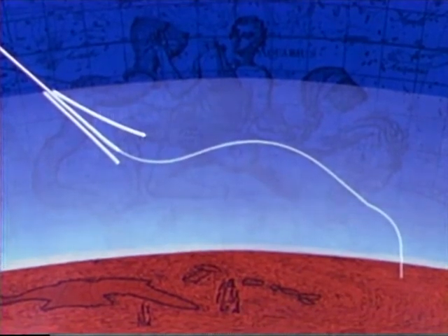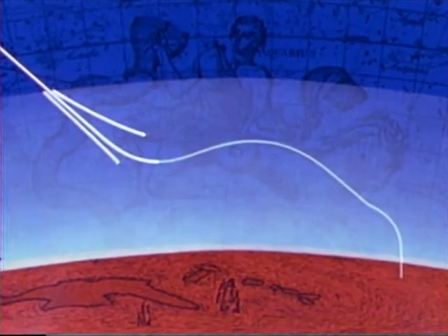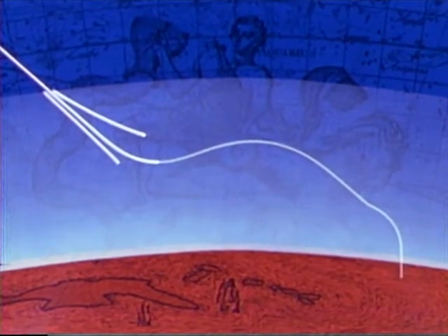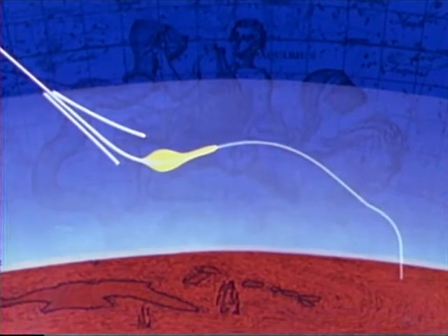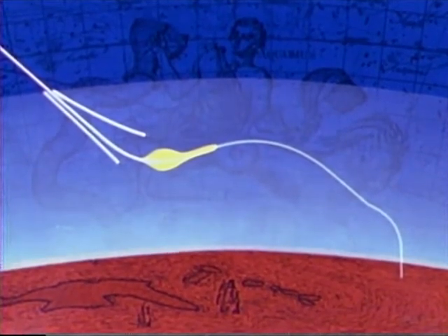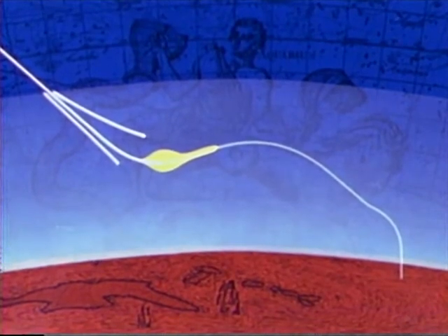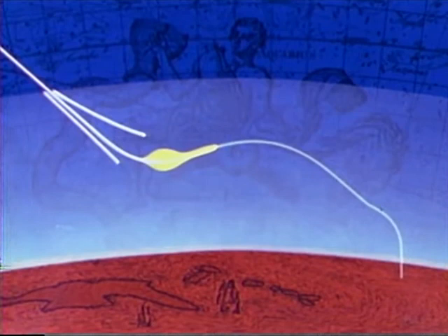The spacecraft continues in a lift-up attitude until it enters the dense portion of the atmosphere. Just before pull-up, maximum G loads will be placed on the spacecraft. Just before this, the first control period begins. During the first 70 seconds of this control period, any error or failure to correct an error could result in what is called, in great understatement, a non-recoverable situation.